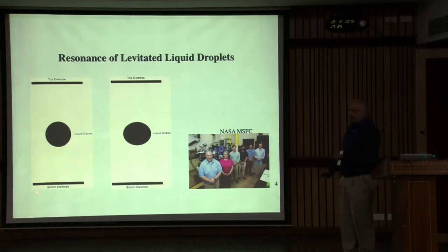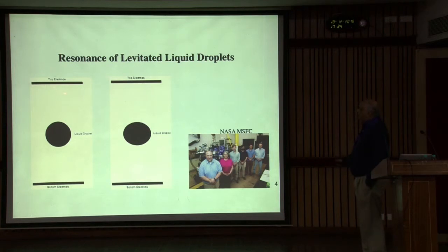I'll pull up the metal using a DC field and levitate the metal in a furnace. The furnace is not yet turned on. Then you heat the metal with a YAG laser, and the metal will, of course, melt completely and form a liquid drop. Then you deliberately change the field ever so slightly, alternate it, so that this metal moves up and down about its centroid position ever so slightly.